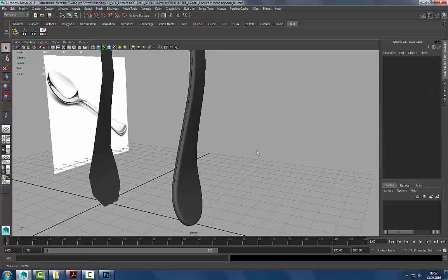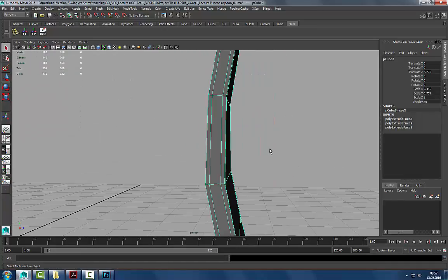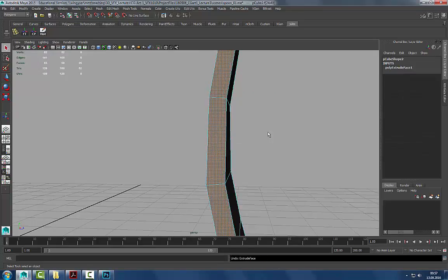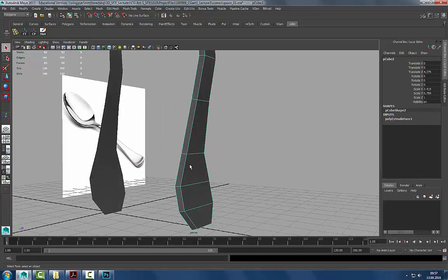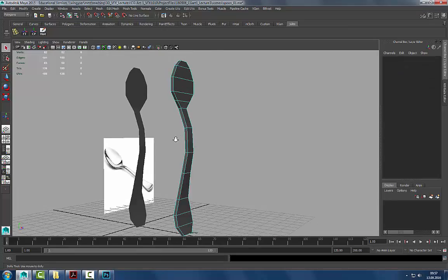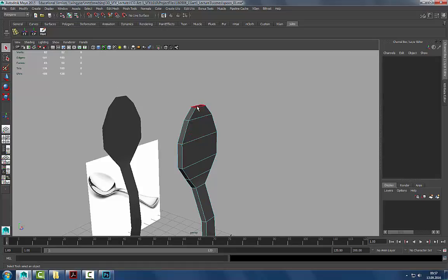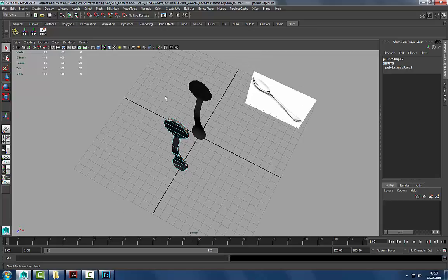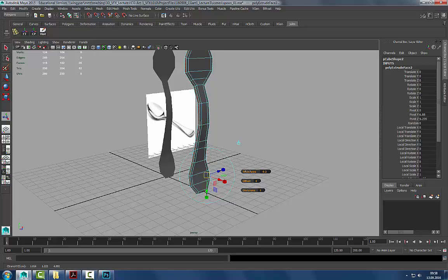All right, so pressing number 3, you can see now, well, it seems to be funkiness with my mesh. Yeah, something funky. So I'm going to do that last little extrude again. But just to take away from this is that you don't always have to use the insert edge loop tool. In this case, it's easier to select this entire face path that just encompasses the object, press extrude, and we get that automatically going all the way around.